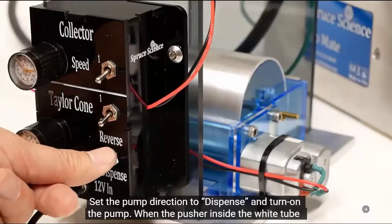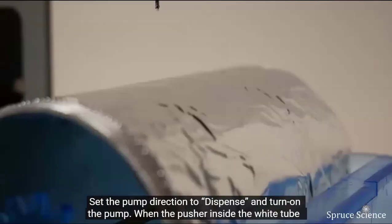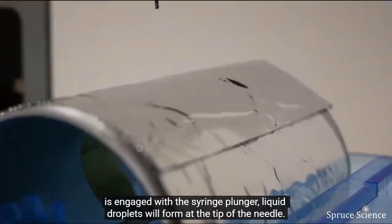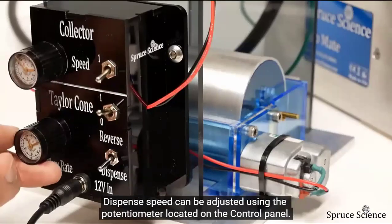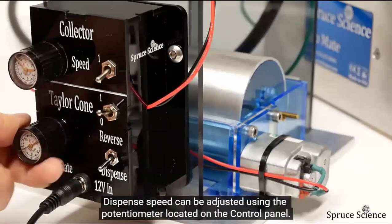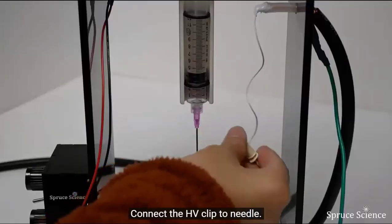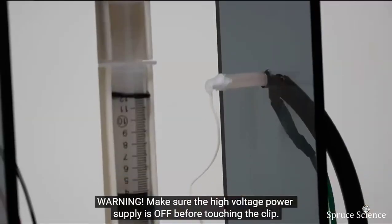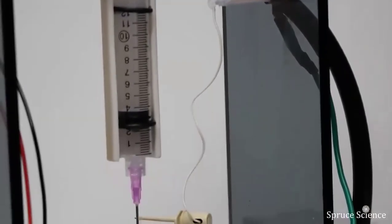Set the pump direction to dispense and turn on the pump. When the pusher inside the white tube is engaged with the syringe plunger, liquid droplets will form at the tip of the needle. Dispense speed can be adjusted using the potentiometer located on the control panel. Connect the high voltage clip to needle. Warning: make sure the high voltage power supply is off before touching the clip.